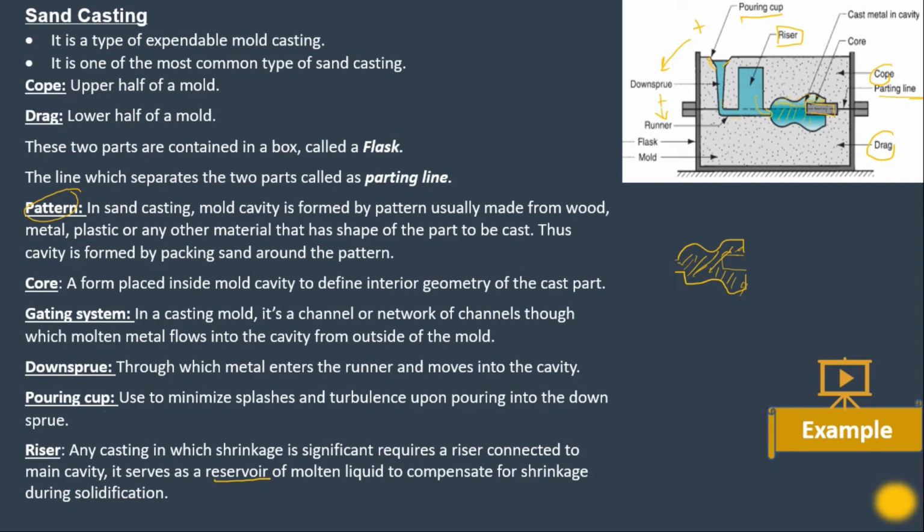And you must have a question: how does it happen that the riser is not shrinking itself while the mold cavity is shrinking and solidifying? It's designed in such a way that the riser solidifies after the mold cavity, or slower than the mold cavity, and we will see in the lectures ahead how it happens in the riser design. So now we will see a demonstration video for this mold cavity and for the sand casting operation.